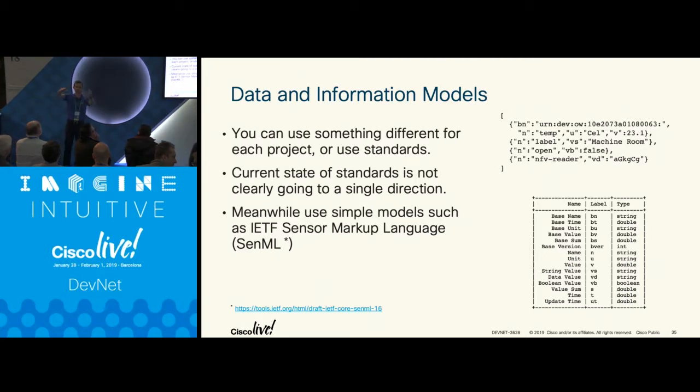Some of them come in XML, some of them are in JSON, some of them have degrees Celsius, some of them have a raw reading on a sensor that does not even translate to anything, and you need to apply some transformation. Example, you have a gauge, for example, that gives you value between 0 and 65,535, depending on the height on a reservoir or a tank. 32,000 doesn't help me. What I need is the number of liters in that tank. And I need that information everywhere, and I need that information to look the same way.